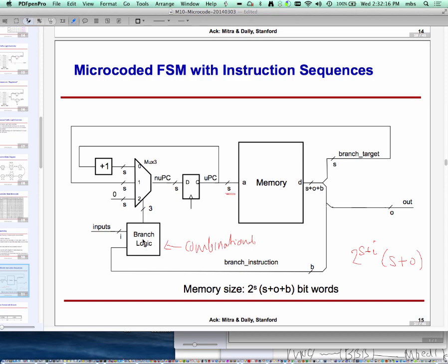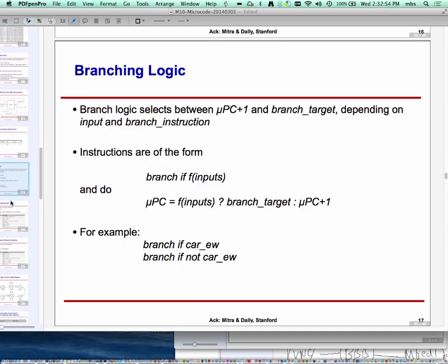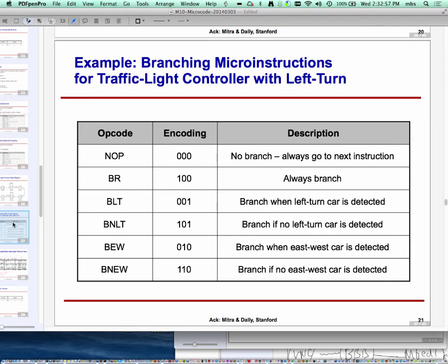Most of the time, you will have a two-way branch. Jump to a target or move to the next one. That's all you would have. And if you're lucky that you're designing your own, then maybe you have a four-way branch or a multi-way branch, but that's kind of rare unless you're designing your own. So if you were to get a four-way branch, would you basically increase your multiplexers by one more? No, you could do that way, but the problem with that is where will you get the target at? Because I don't want to increase the size of my instruction, so I still want only one target address. Okay, so this is something I had described last time, but let's just go over it quickly.